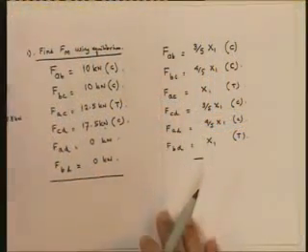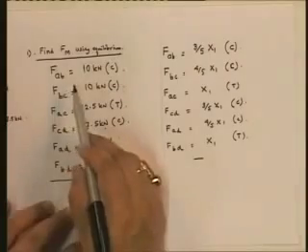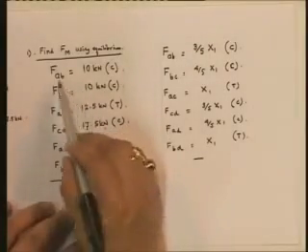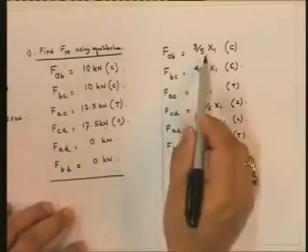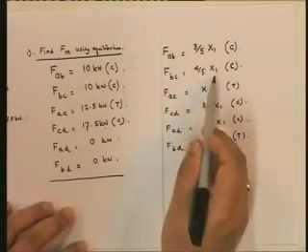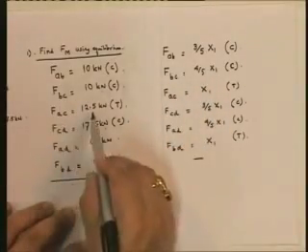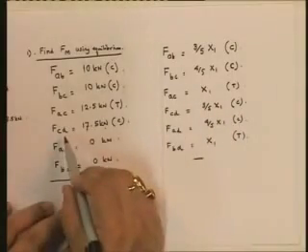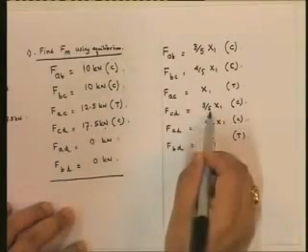Okay, and therefore if you look at it, what would be the force in the original structure? It would actually be, if you look at this, that the actual in the original structure FAB would be equal to 10 plus 3 by 5 x1, BC would be 10 plus 4 by 5 x1, AC would be 12.5 plus x1, CD would be 7.5 plus 3 by 5 x1.